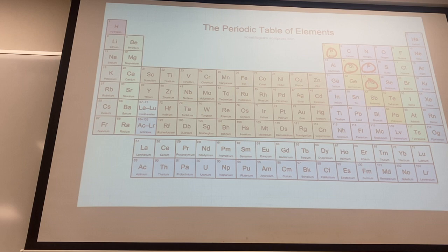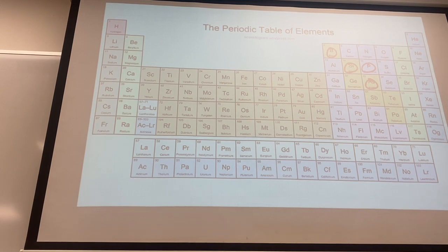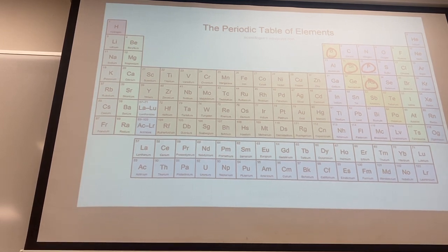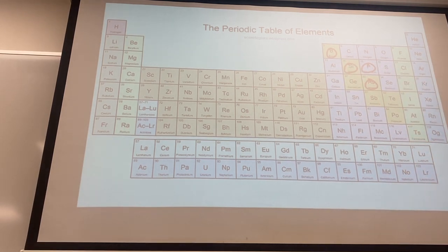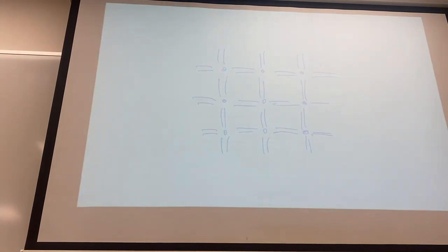Oh boy. Yeah, hard shift into all of our semiconductor related things. So, where we left off, we were talking about how we start with silicon. It's a semiconductor that is neither an insulator nor a conductor, but kind of in the middle. If we artisanally infuse a lot of boron or phosphorus or arsenic into silicon, we change its conductivity, and we change what the crystallographic structure looks like. So we had just started to talk about what that looks like in a 2D illustration.